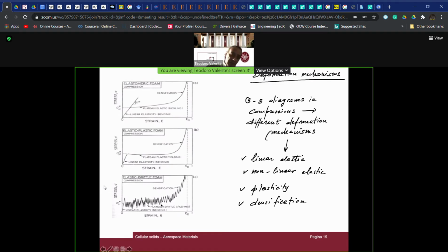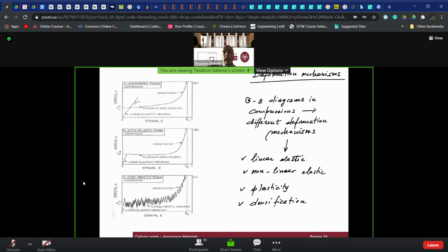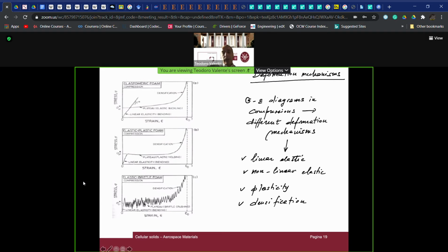But we have, as you see here, a more fragmented diagram, even though when we reach the limit stress for the elastic behavior of the materials itself, we can have, without significant increase in applied stress, a very relevant response in strains. A sort of plateau also in this case, but a sort of interpolated plateau due to the fact that the curve is very fragmented.